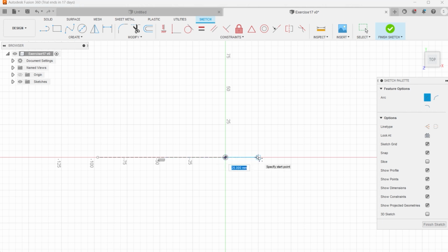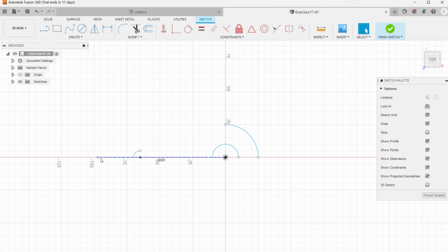Here it will be two concentric circles. The radius will be provided later on, right? And here also some distance, how you can make one circular arc. And again we can join some straight lines from here. So initially we are making the object, and later on we'll provide a smart dimension to provide the actual dimensions, right? And you can see that this one is having radius 15 mm and this one is 10 mm.